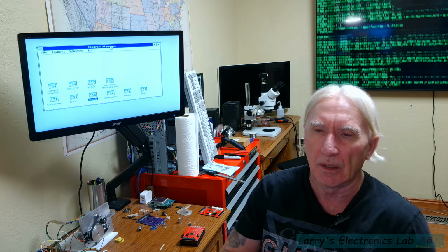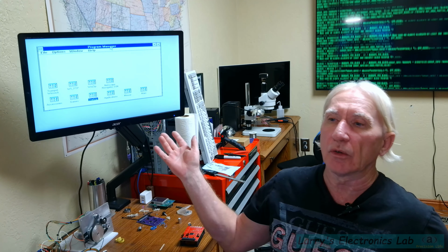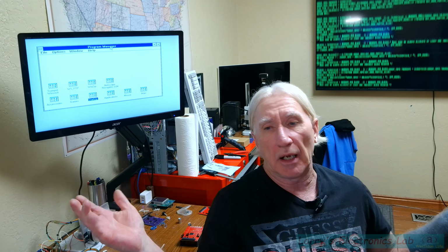If I have LEDs on the board and a scope, I can pretty much debug about any code that I've ever written anyway. So you can always write some kind of code to trap errors or send out a signal to light an LED or send a signal out on a pin to measure with the scope or something. So I don't really mess around with the in-circuit debugging. Maybe once my code gets more complex, maybe I'll need it. I don't know. But right now, I haven't had to do that yet.